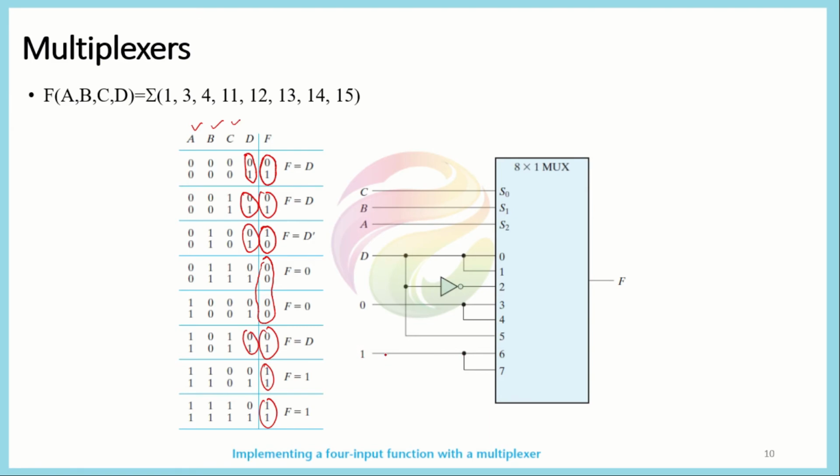So in this way we can represent any given boolean function using the multiplexer. We have seen two different ways of representing it. The second method, which we discussed in this slide and the previous slide, is the more efficient implementation, because in this we are using a multiplexer with a reduced number of selection lines for the number of inputs with which we can implement any given boolean function.